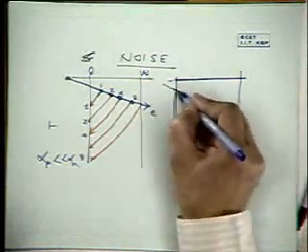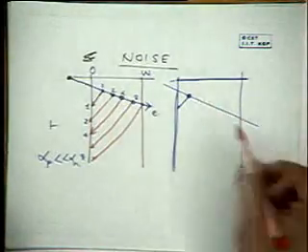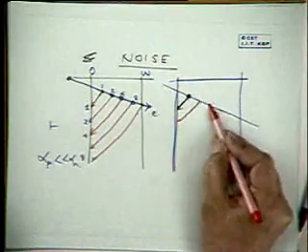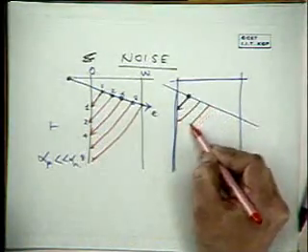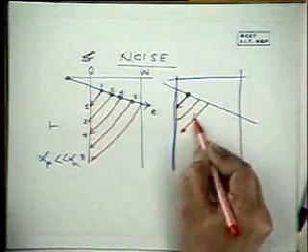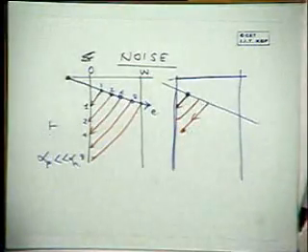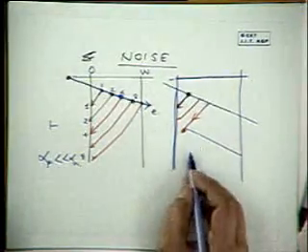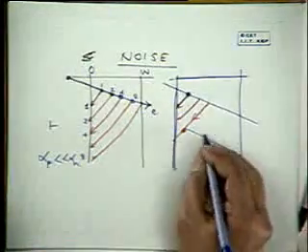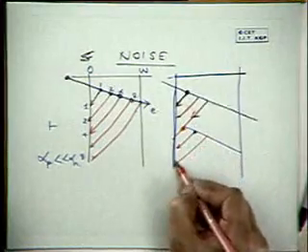Then you have an electron trajectory there, okay, and the holes are multiplying. Electrons are creating electron hole pairs, but then suddenly a hole here will cause multiplication. So as a result, what will happen? The electron hole pairs will branch out, and here again multiplication will occur. So holes start multiplying there.